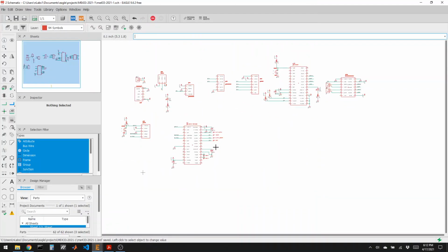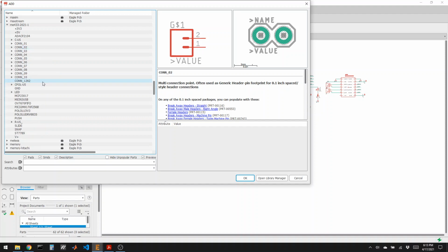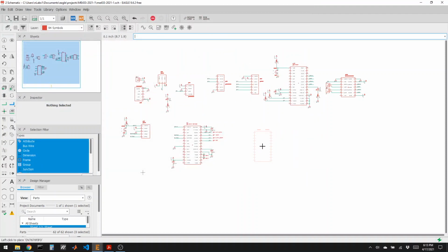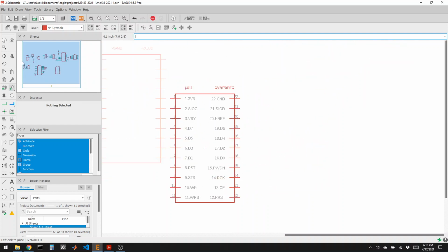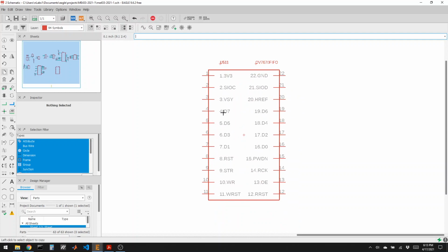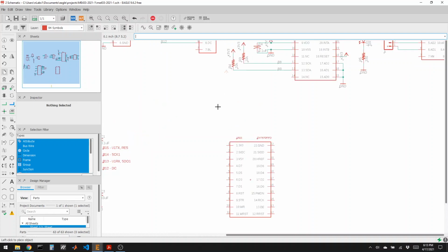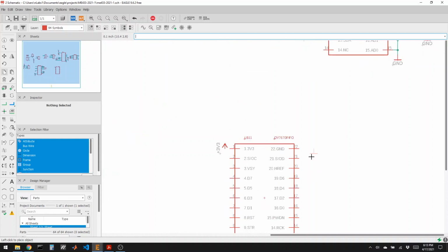And we're almost done. So the last thing we have to do is add the camera module. So cameras are notoriously hard to work with because there's just so much data that comes out so fast. This camera module has a FIFO memory chip built in. That'll make it easier for us to slow down the rate of data, but the data still comes out as a parallel port. So from D0 to D7, that's the data. Every byte will read a bit from 8 pins at a time. And then there are lots more pins that control the flow of the data, as well as power and ground. So let's go grab a power and a ground. 3.3 volts, ground.